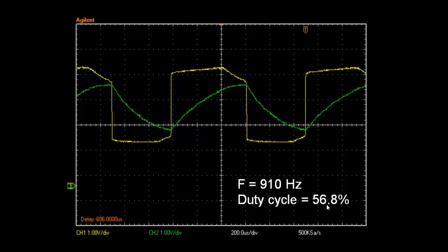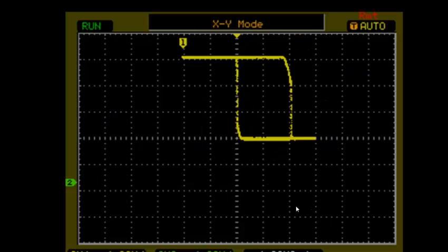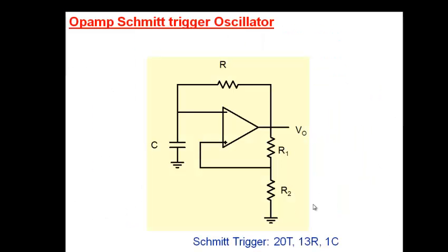You can get very close to 50% also. So you can make a design which is very efficient, but it will take you effort to design, because of all the tight coupling between the Schmitt trigger and the RC. So what you can do is you have to design the Schmitt trigger oscillator that I'm talking about. In addition, you can also design this side by side, this particular one, and you can see how well this works as compared to the other one.